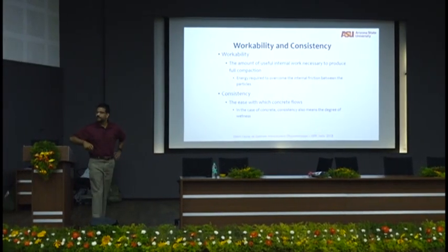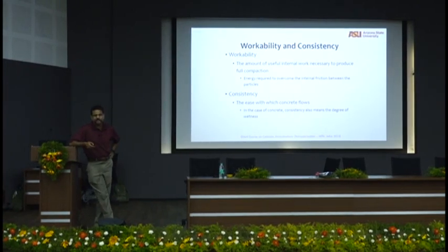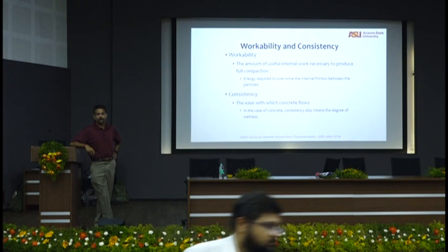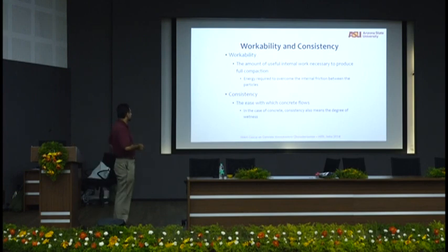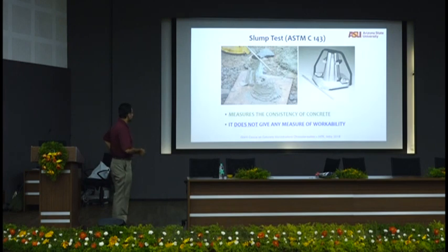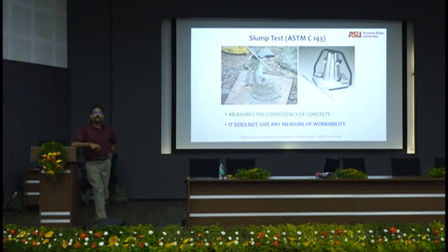A lot of people mix these terms together and use workability and consistency together. They are not the same. Workability is the energy required to overcome the frictional forces. Consistency is the ease with which you can make the concrete flow. So slump does not measure workability. Anybody who tells you slump is a workability test is wrong.